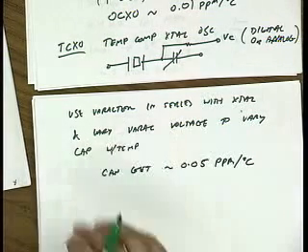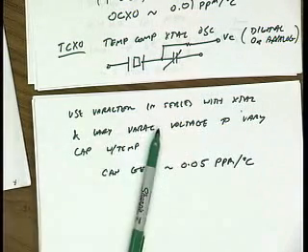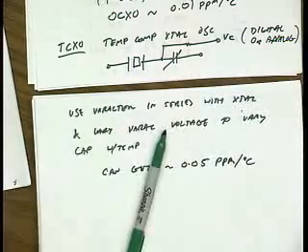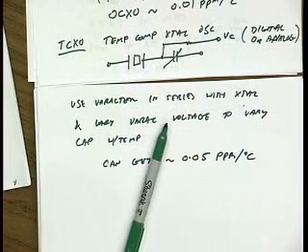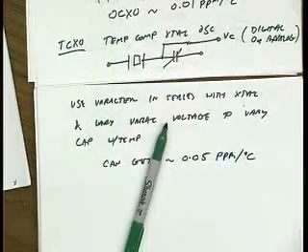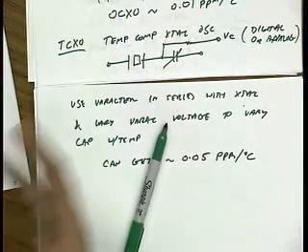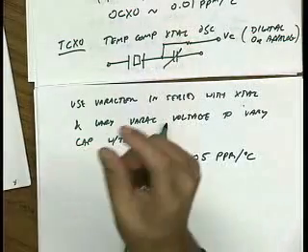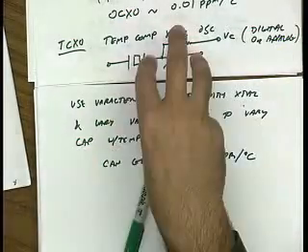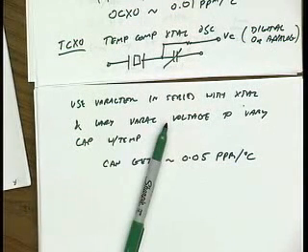Incidentally, the same kind of techniques can be used with MEMS resonators. When people initially designed MEMS resonators, one of the concerns was that you cannot get the same temperature stability that you can get with a crystal resonator. But using the same kinds of techniques, digital comes for free, so the logic to implement this might just be a tiny little area on your chip, and so you can compensate for those variations.